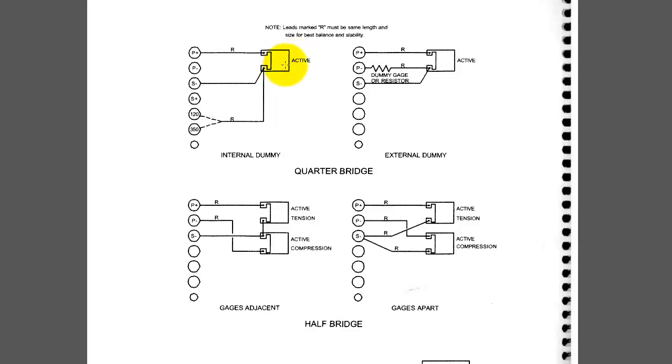Strain gauges also come in 350 ohm varieties, so you have that second option should you need it. And then to mitigate for temperature changes on the lead wire, we have the second wire connecting to the signal corner on the Wheatstone bridge.